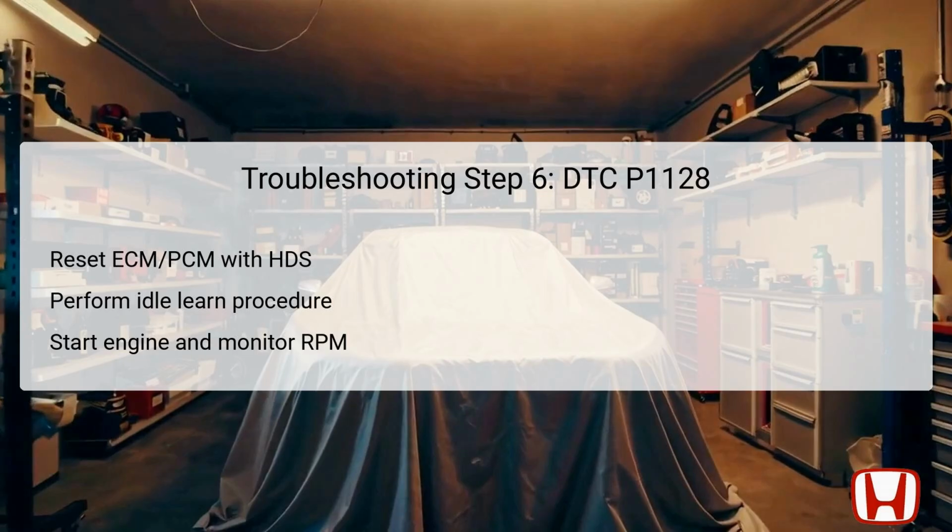After these steps, start the engine and hold it at 3,000 RPM until the radiator fan engages, and then switch to an idle state. This systematic approach ensures that the ECM's adaptive strategies are updated, ultimately enhancing the performance and reliability of the new MAP sensor in the vehicle.